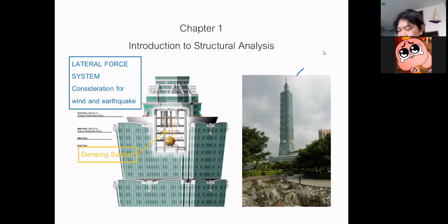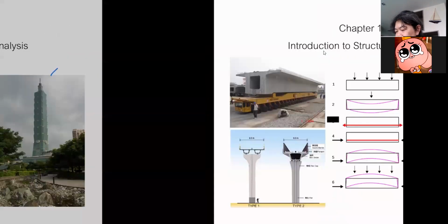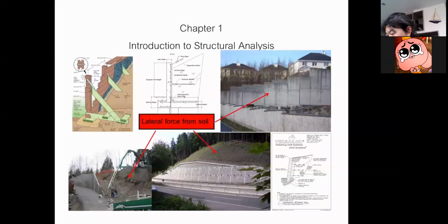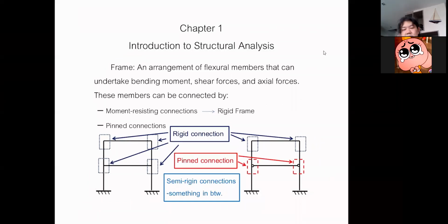And this building is quite a challenge, because not only do you have to design for typhoon, you also have to design it for earthquake as well. Okay, good challenge. Anyway, let's skip this. We don't need this. Okay, so this is the first picture. When we need the structure of the frame, we generally need our joint here. This is the joint where members meet to be rigid. If it is a pin connection and the moment there is 0, you may not have a system that is strong enough to withstand the lateral load.